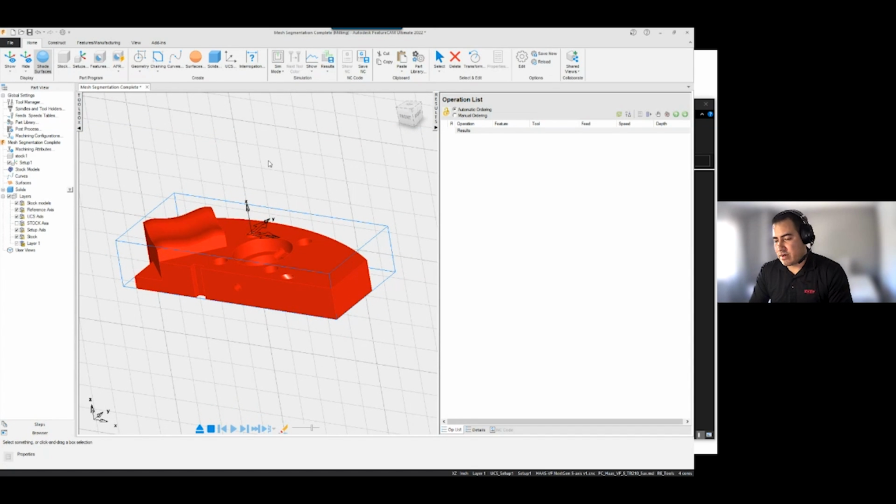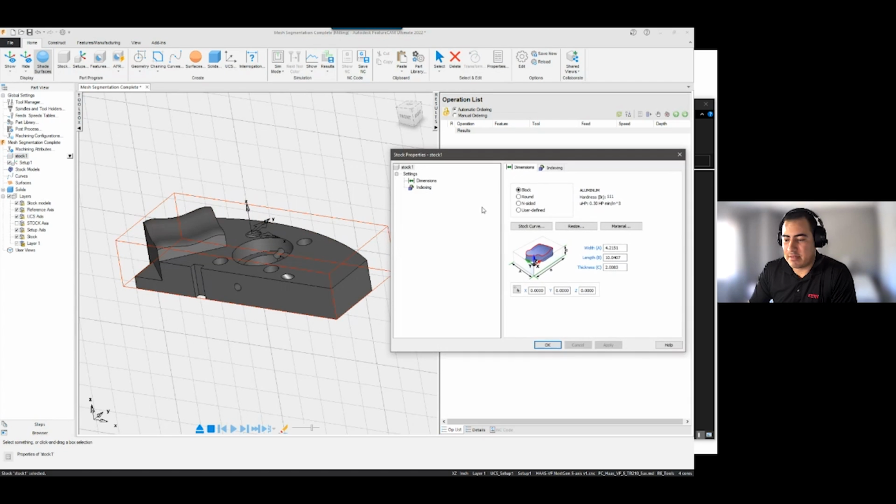The first thing that I always recommend customers do when they're working with the software is make sure that you not only have obviously the correct NC file, right? The post. You typically, a post comes with the actual machine simulation file as well, if you guys take a look down here at the bottom of my screen. And then you also have to make sure you set up your tools correctly, right? So why is that important? Well, the way that FeatureCAM works is that it takes a look at your tool library, and it actually takes a look at the stock type that you're working with.